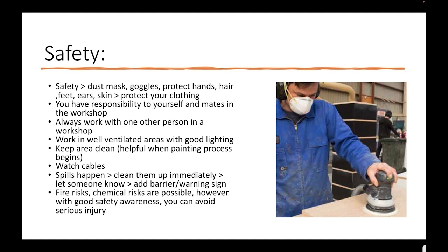Ideally, you should have a drop power plug in your workshop, but in reality, we often don't have that at home if we're working in a garage and so on. So it is important to think about how you wrap the cable around you over your arms or shoulders to make sure that they're not in the way when you're cutting through some heavy timber pieces.